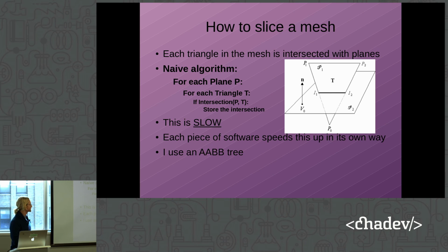Mesh slicing is often a really slow process. Not really slow, but it's hard to get it to go very fast. Basically, you decide how many layers are going to compose your part, and then you take each 2D plane and intersect it with one of these triangles, which yields either a point, a line segment, or nothing at all. You can just discard all of the points, and then you're left with a series of line segments in each layer. Each of these line segments describes the outside walls of your part, so these are the meat of it. But there's not enough structure in these line segments for us to do very interesting things with them, so we need to process them again.